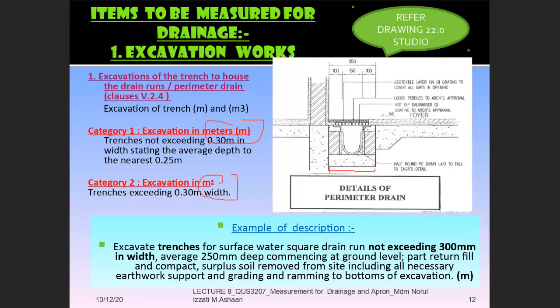Look at the scale properly, class. What is the scale used for that particular drawing? 1 to 10. So 1 to 10 is about 10 times smaller than the normal scale or normal ruler. Okay, so 1 to 10 is 350. I just want to get all of you to be ready with the scale ruler as well, because I would like you to check. Look at this information. The width has already been given as 350, but just for you to double check your usage of the scale ruler.